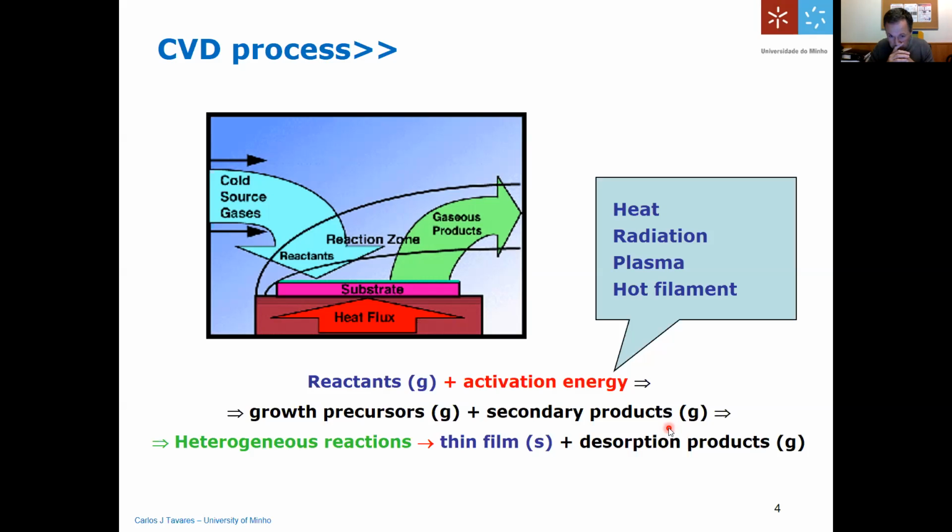And when a methane gas or hydrogen gas passes through the filament, if the temperature is high enough, above 2000 degrees C, then this heat can break down the molecules. For example, you can separate the hydrogen from carbon in methane, or you can break down the hydrogen molecule into atomic hydrogen, for example, if you want to make a heat treatment in a reducing atmosphere, okay?